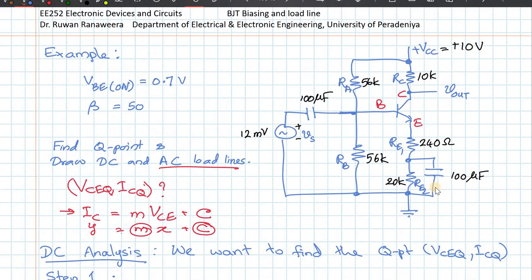If you look at this circuit, I'm going to open circuit this capacitor here, this capacitor and this capacitor. If I open circuit this, there is no connection here, so it is broken from here, and this capacitive part right here is also not there. Therefore all you have is RE1 plus RE2 here. So let me draw this circuit once again.